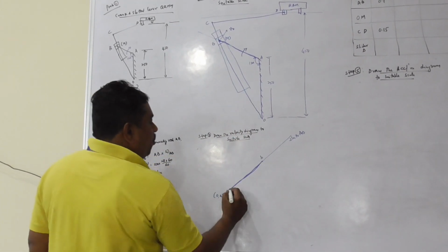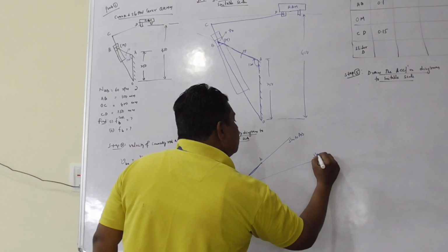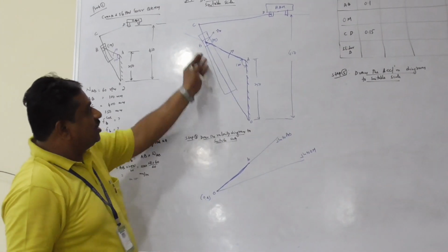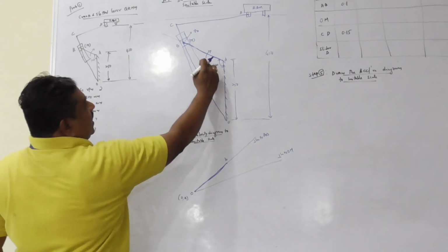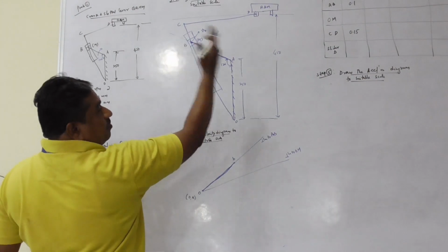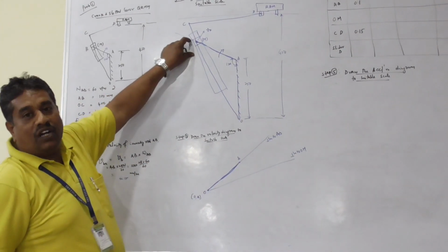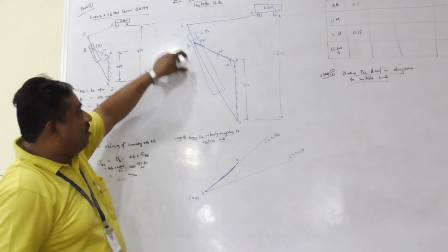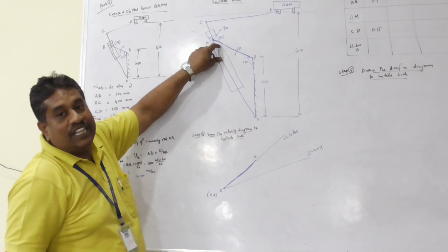Therefore, through the pole, draw a line perpendicular to OM. Direction is known, but magnitude is unknown. Now, as the connecting rod rotates, the oscillating link OC oscillates between two extreme positions. During this course of action, the die block, the piston, which slides inside the slotted lever at the given instant of time, that moving point comes and coincides with M.